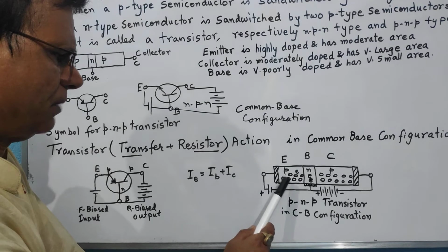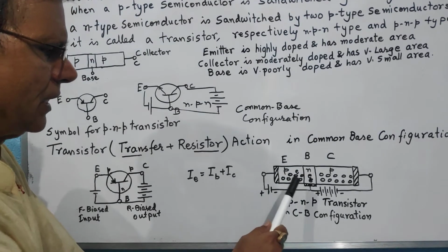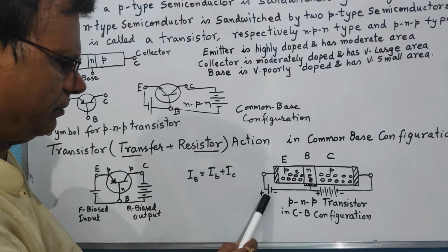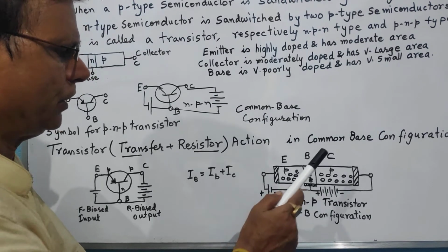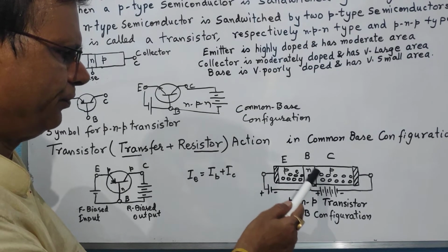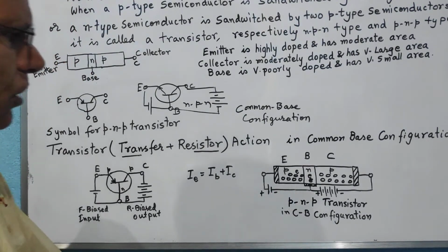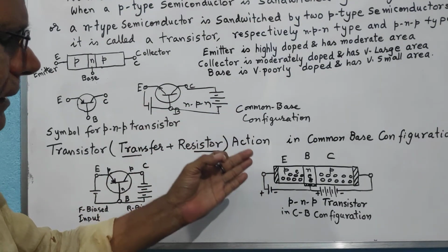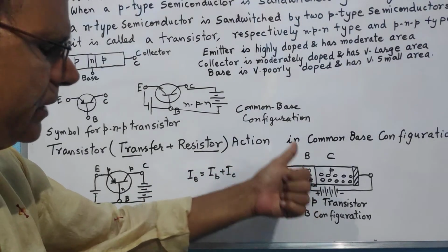You have forward bias, the input circuit, that is emitter and base is forward biased, and therefore under the influence of this forward bias voltage, the holes of the emitter are pushed into the base region where there are only few number of majority charge carrier, that is electrons, because we have already ensured to get this situation created by doping the base very poorly.